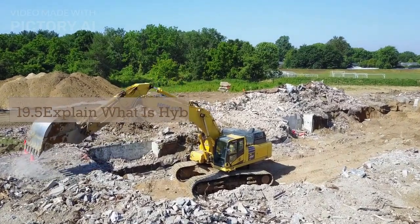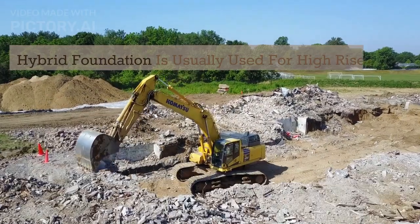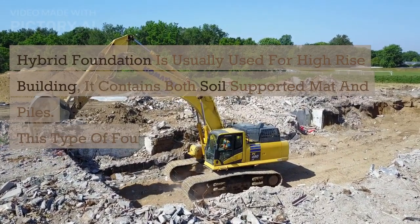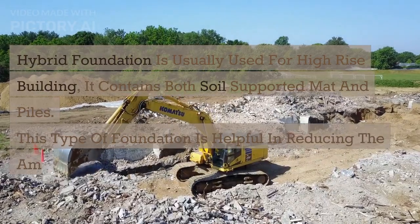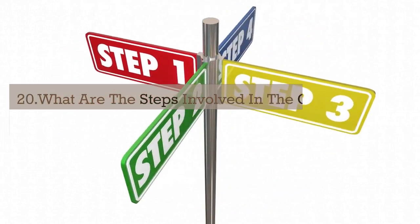19. Explain what is hybrid foundation. Hybrid foundation is usually used for high-rise buildings. It contains both soil-supported mat and piles. This type of foundation is helpful in reducing the amount of settlement. 20. What are the steps involved in the concreting process?